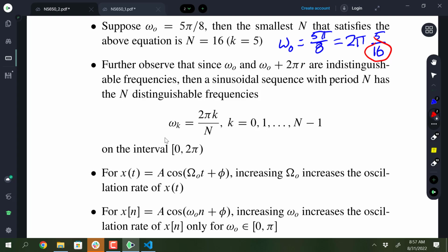But if you were to go to 400 and then go to 1100, that would be 100 hertz above the sampling frequency. That would be going up to the next band of frequencies. 0 to n minus 1 would correspond to 0 to the sampling frequency minus 1 over n.